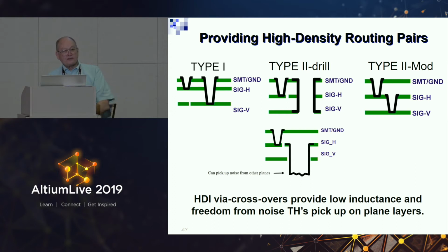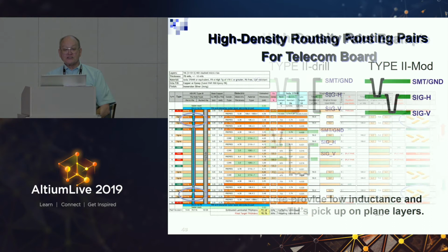And so I always recommend that your most sensitive electrical nets are routed closest to that surface ground flood for coupling. And because there's so much higher density, by the time you get most of that routing done, the rest of the non-critical routing can be done as a conventional multilayer in the center cores, as well as the rest of the power distribution.